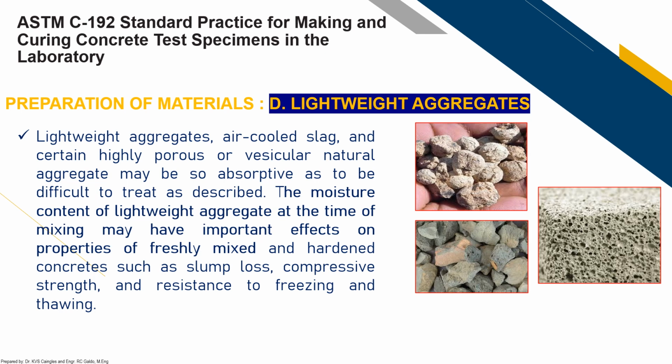So it is really very important to determine the moisture content of these aggregates at the time of mixing, because it would affect the properties of the freshly mixed and hardened concrete, such as slump loss, compressive strength, and resistance to freezing and thawing. Okay.